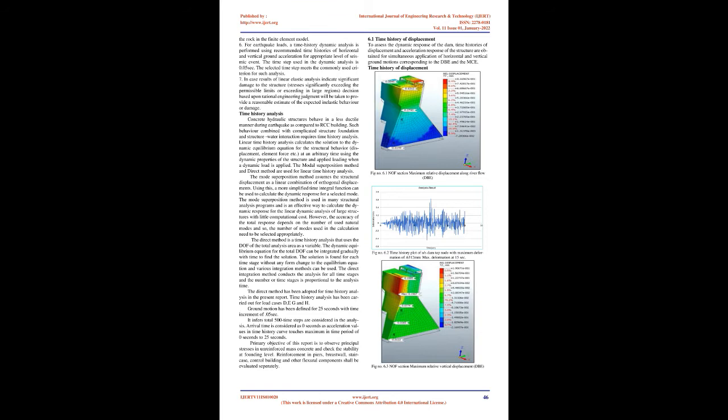6. Analysis. The finite element model described earlier has been subjected to various loads mentioned earlier in the report, and a detailed analysis is carried out to determine resulting deformations and stresses within the dam. While the static loads are applied as one-time loading, the earthquake loads, both the DBE and the MCE, are applied in the form of appropriate time histories of horizontal and vertical ground acceleration.